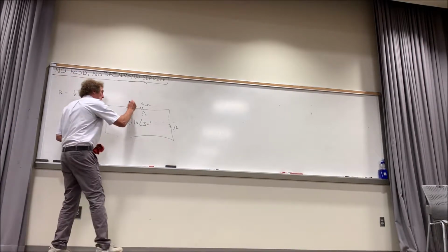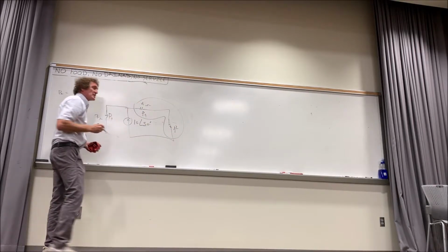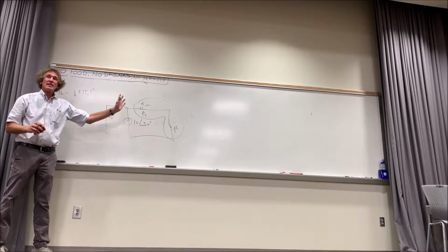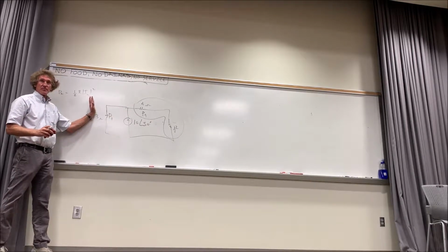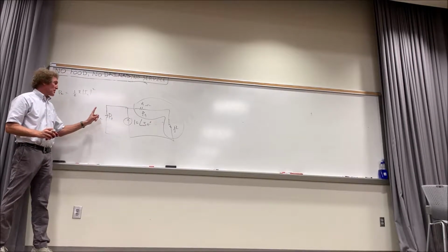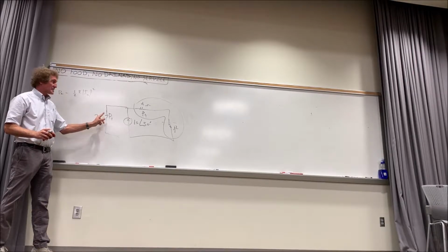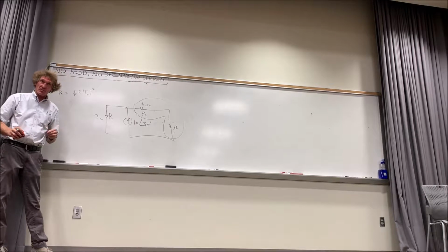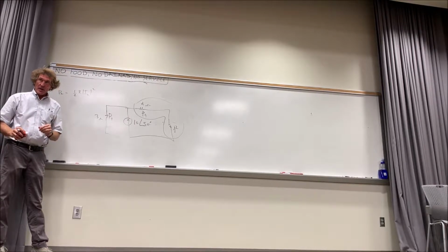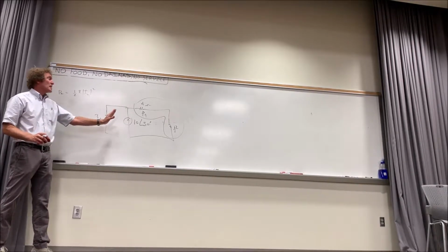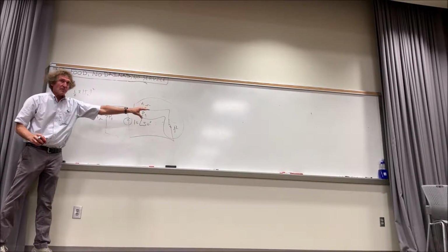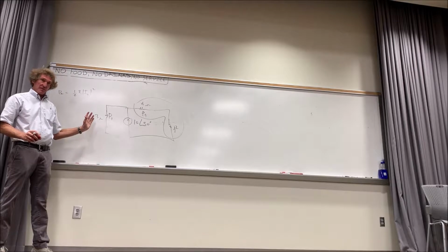Do you see that these 2 elements are in series, and they're in parallel with this one? So if I want the current here, the total current is 10, going into this parallel combination. If I want the current through here, it would be 10 times the opposite impedance over the opposite impedance plus that impedance.